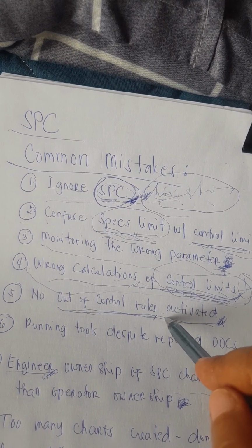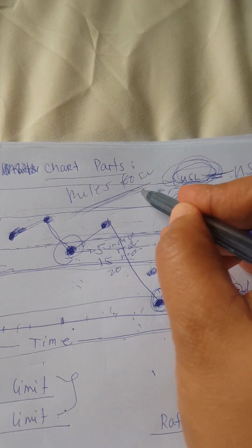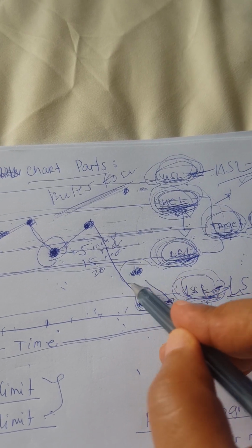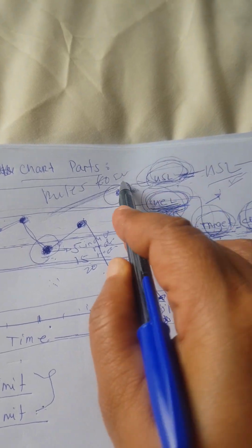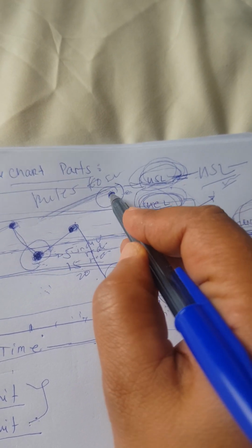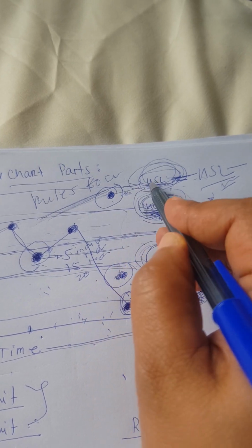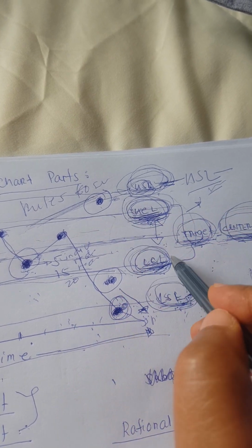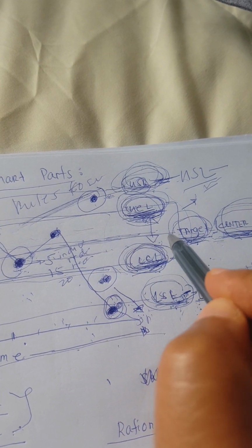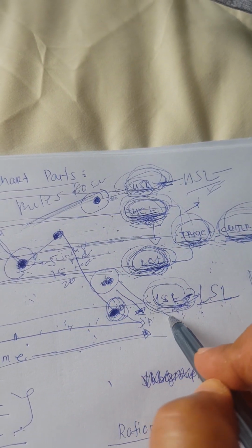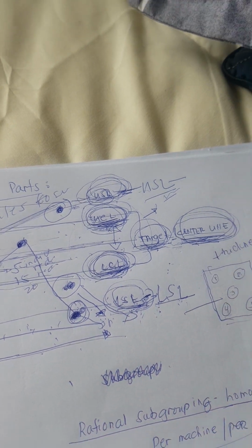Number 1 is one point outside the upper control limit, or outside the lower control limit. Why do we need to consider this rule? Because if our process has this out of control already, it's nearing the specs limit already. That is why the control limits are our guard. They guard our process against any potential issue that may lead to not meeting the customer requirement.